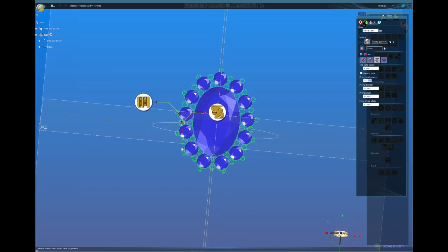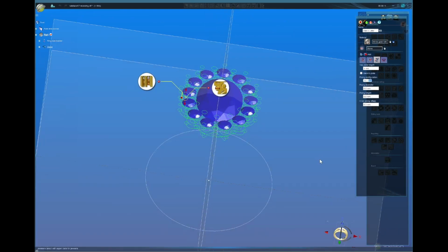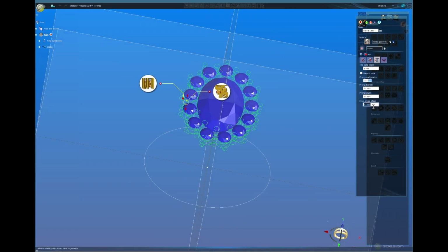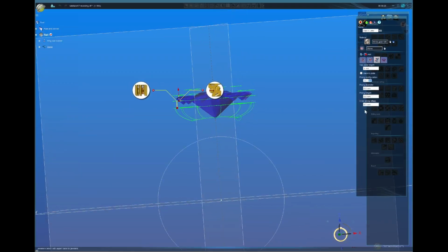And prong height, for now, I'm gonna leave as 0.8 also. And prong offset is the inside. See, when I move, it changes this side of only the inside prongs. I'm gonna leave the same height as the other ones, so we're not gonna do any offset for this.